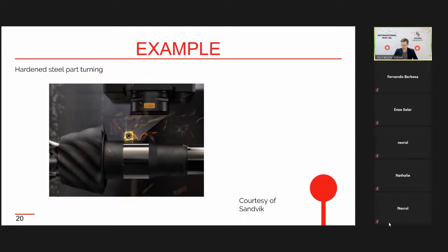For example, if you are familiar with some wood cutting, I'm talking about wood cutting because it is a hobby for some of us, and we can sometimes, for example, drill some holes in some wooden parts for our homes, for example, for some furniture and so on. And if you are familiar, you know that when you cut wood, temperatures are very high. That's why you should avoid excessive heating of the cutting tool. And if the heating is excessive, the cutting tool will become dull, not sharp.